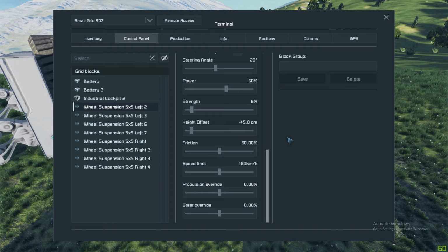The center of gravity on your rover matters. If it's a high center of gravity, if you've got a very tall design and you turn suddenly, it's going to flip over. If you have a very wide wheelbase and a very low center of gravity, you can have that angle quicker and it will maintain itself a lot better. But again, you need to adjust these to your own preferences. The generic setting of 20% is fine for most things.